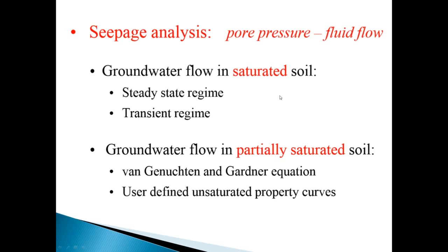And then seepage analysis, once again, which we'll go over today, so you can study steady state as well as transient regimes to see how the pore water pressure changes as the water level changes. You can account for different rainfall conditions, etc.